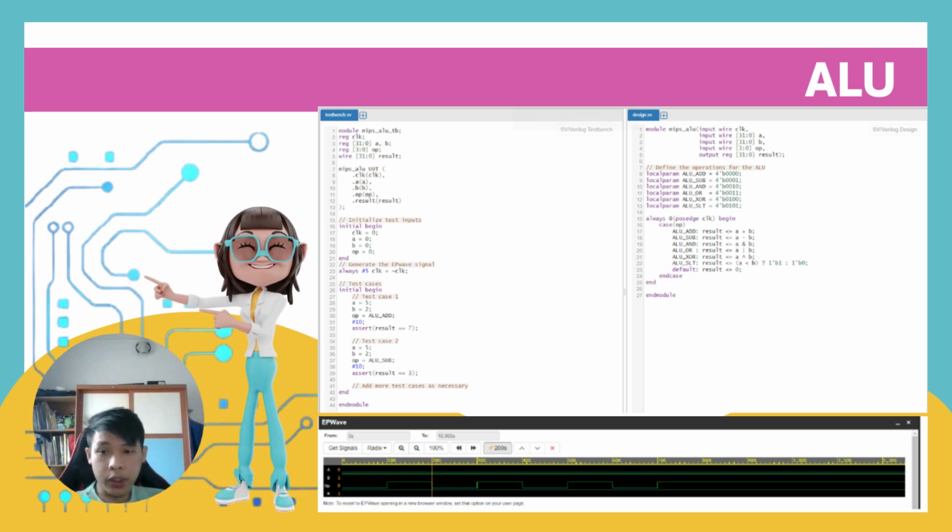For the ALU, it supports 6 operations in a combinational circuit that calculates a 32-bit output based on two 32-bit inputs and a 4-bit input specifying the ALU operation to perform. So this is the code to create the ALU, and its EPWave is recorded.